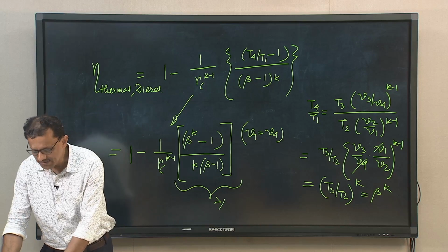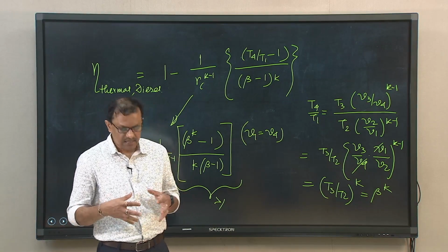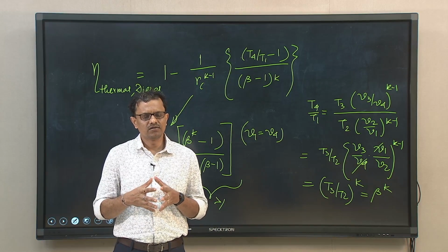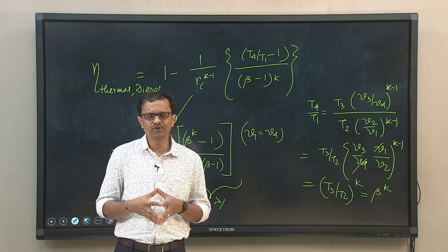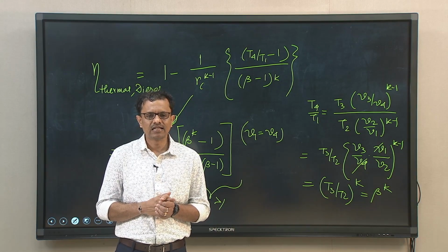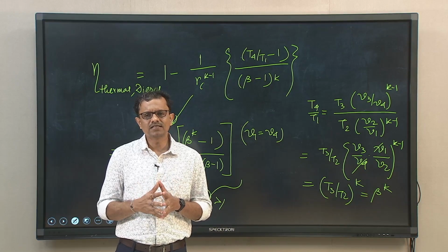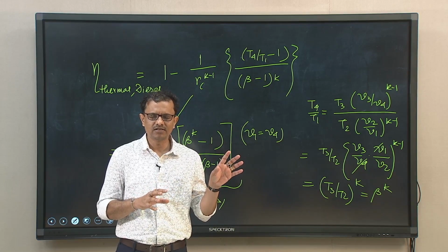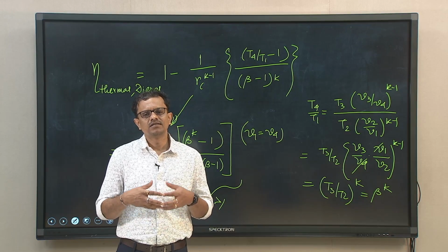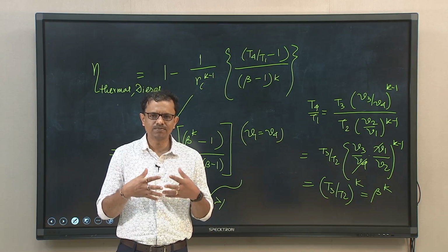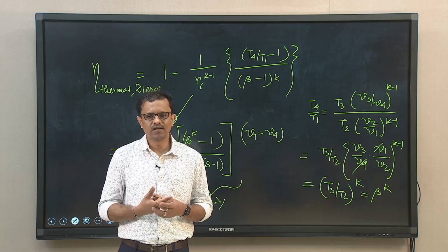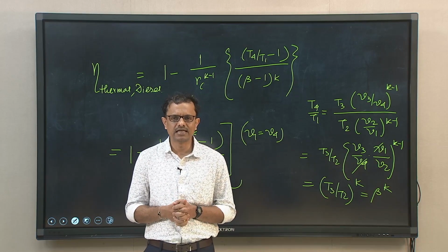So, to summarize today's discussion, we have discussed the basic cycles typically used to map several processes of both 4-stroke cycle SI and CI engines, essentially to estimate their performance efficiencies. And then we have briefly discussed several processes in different thermodynamic planes, and from there we have tried to express the mathematical form of the indicated thermal efficiency of both 4-stroke cycle SI and CI engines.